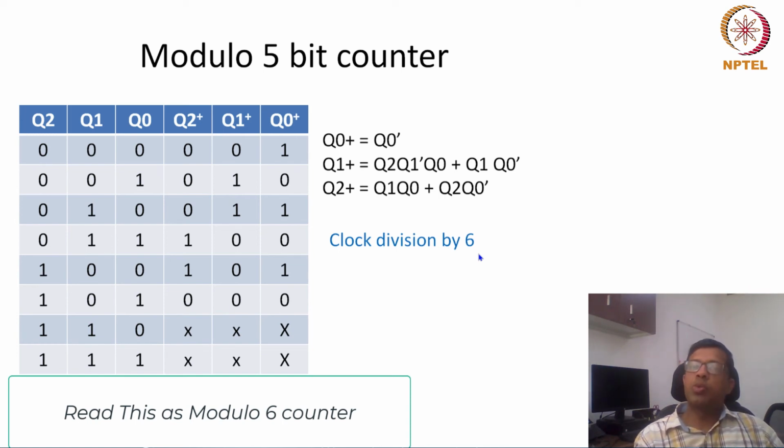Yes, it may also be worth saying here that clock division is easier to do using digital circuits, essentially using flip-flops. But clock multiplication, let's say the input clock is 100 megahertz, there is no clear or systematic method that can help us in achieving a clock of 200 megahertz, or a clock which is faster.